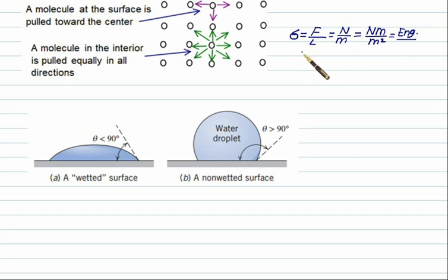What is observed here is that, suppose I show molecular levels, all molecules on the top surface, then we have a second layer of molecules, a third layer and a fourth layer. If you see this molecule, it is surrounded by the same molecules, so it is pulled equally in all directions. But the top molecule is pulled in a downward direction, and we have another molecule of different material. In that case this film will get stretched, and when the film is stretched, tension comes in because of this second layer of molecules. That is called the surface tension.